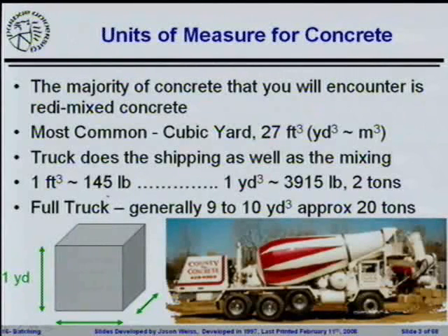Now, the majority of the concrete that you are going to encounter in your life, depending upon what application you are in, is likely going to be ready-mix concrete. Most common way that this is going to be ordered, at least in this country, is by the cubic yard. You could order it other ways if you would like, but most people are going to translate that over for you into cubic yards, at least in this country. Other countries, you may be able to order it by the cubic meter. What you will find out is a cubic yard is very, very similar to a cubic meter, although they are not exactly the same.